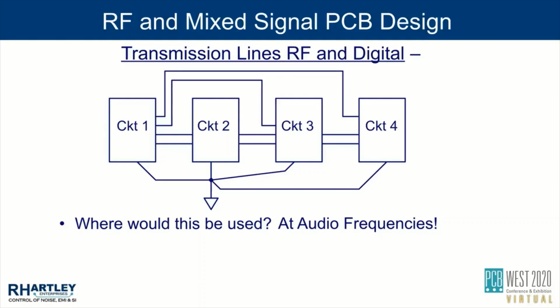If you take the bottom wire going from circuit 1 to circuit 3, you ask the question, where's the return path? The return path is in the quote-unquote ground wire from 3 through the star point and back to 1. And this whole concept works no matter which wire you put signal in relative to ground. You can see where the return path is going to be from circuit 1 to 2 or 1 to 3 or 2 to 3 or whatever. We can see how things are going to function.